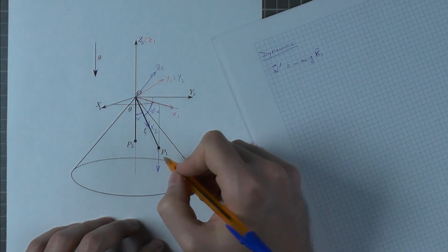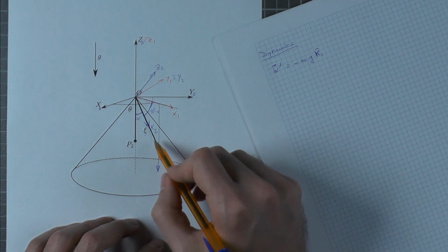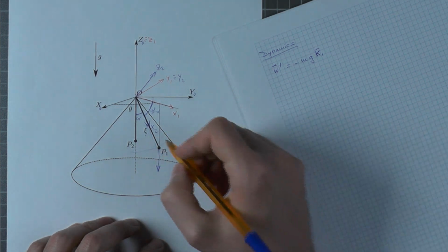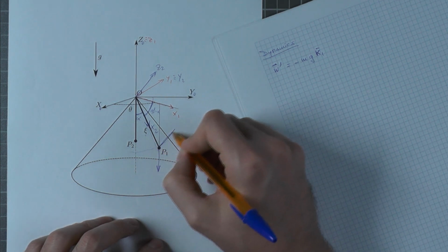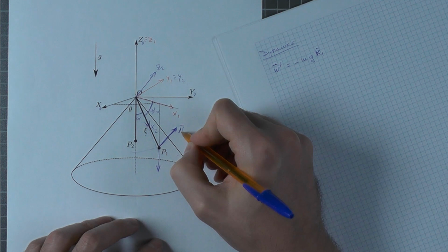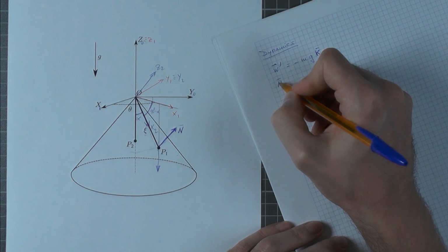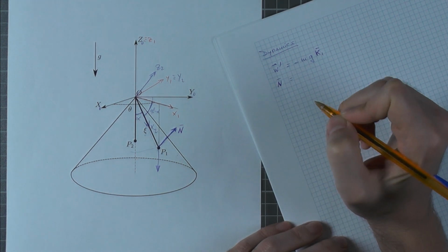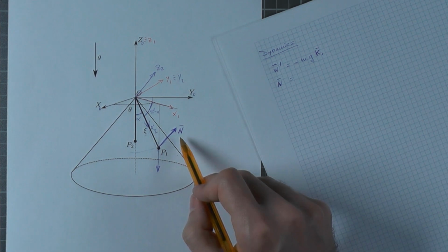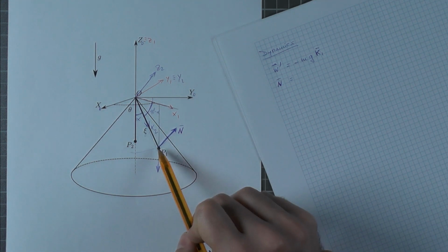Now, on P1, there are two additional forces acting on it. The first one, since we are on the surface of a cone, okay, and the particle cannot move perpendicular to it, there must be a reaction force perpendicular to the surface of the cone, which we are going to call N. Okay, this normal reaction force is a reaction force, and therefore we don't know its magnitude, okay, but we can at least provide its direction. The direction of N is the perpendicular to the cone, as I said before, so we actually have a vector in that direction.